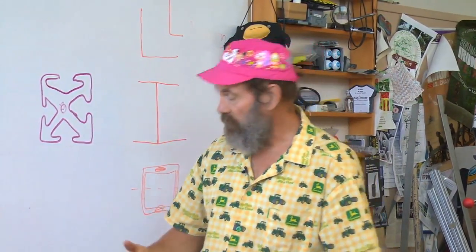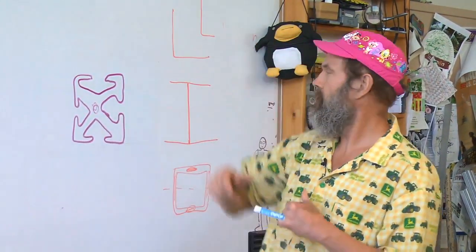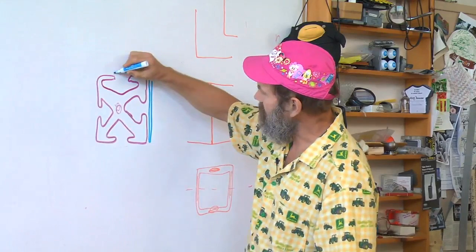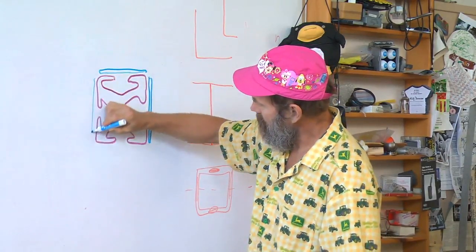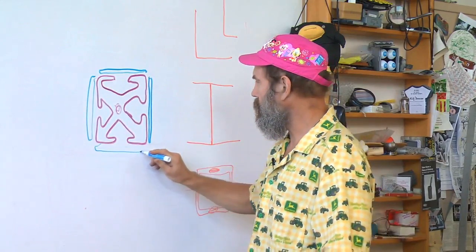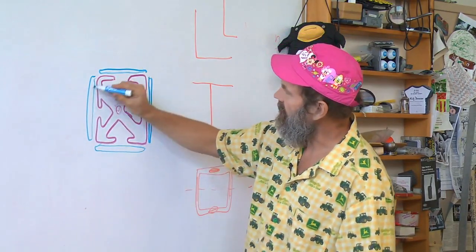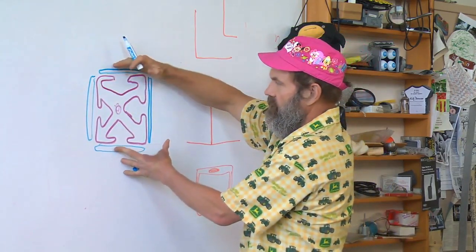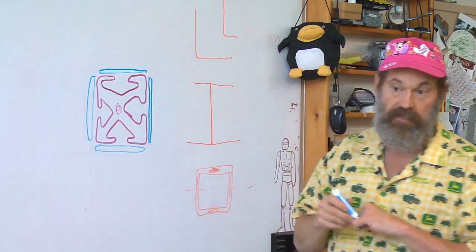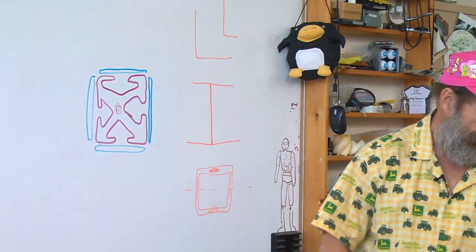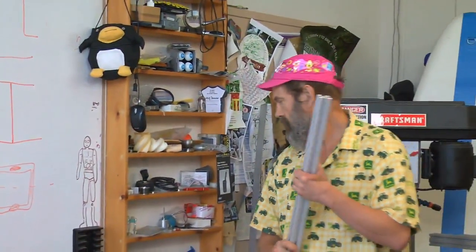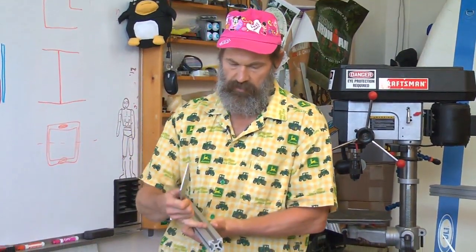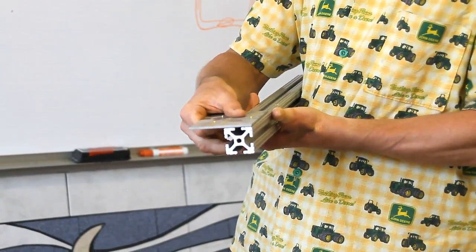So while I've been burbling away, you've probably been thinking, yeah, I've got the answer. I somehow need to close the sides of this. If I could somehow close the sides, I would now have a closed path for the torsional structural loop. Indeed, I would also be adding mass far away from the neutral axis for bending resistance. And there's a couple ways you could envision doing that. You can envision building your entire machine out of this stuff and then taking thin sheets in the parts that are exposed and attaching them.